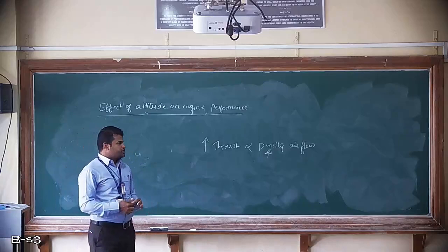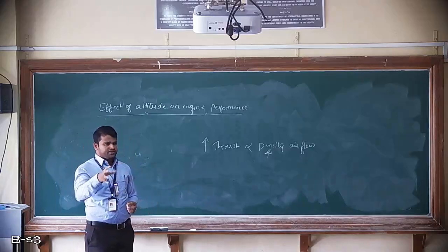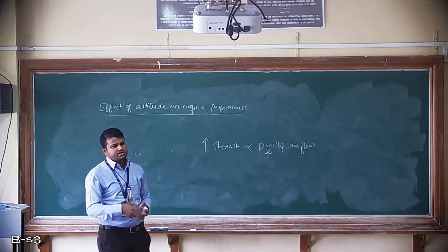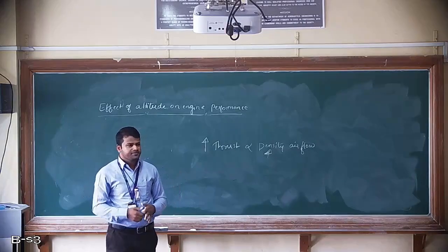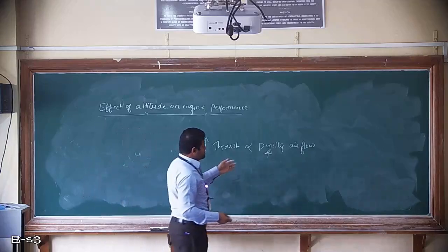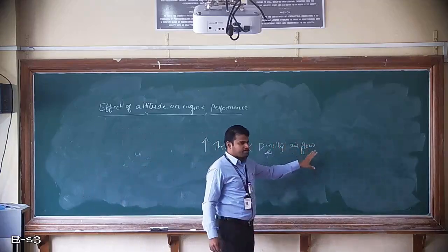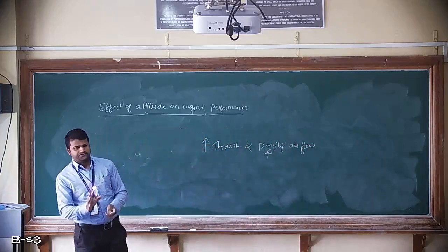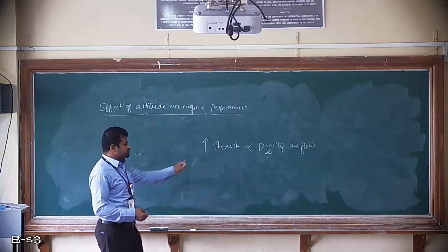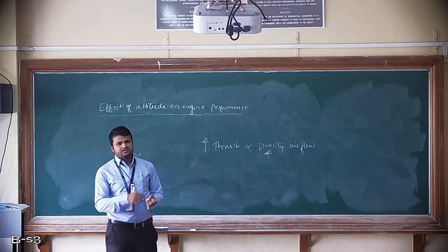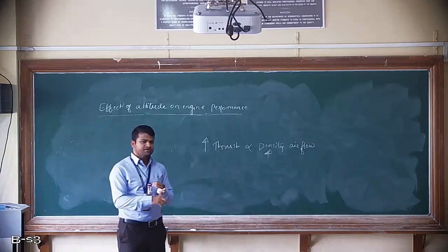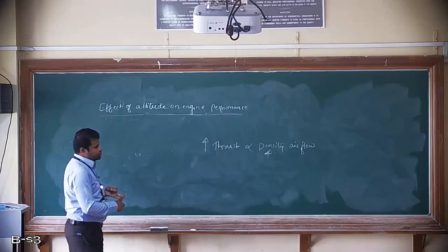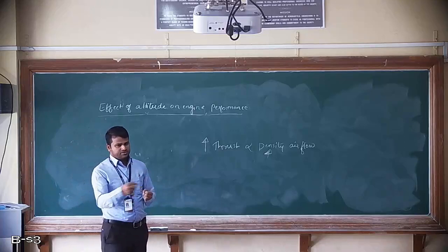First of all, the air density is less, and on top of that, due to temperature, the air molecules spread here and there, so you will not get enough mass flow rate. So this is related to aircraft performance. One thing is it will produce less thrust, second it will consume more fuel, and third is the aerodynamic part, which we will see later.